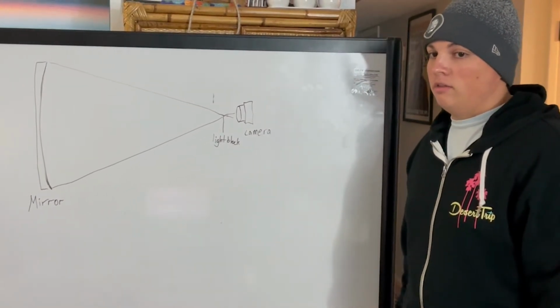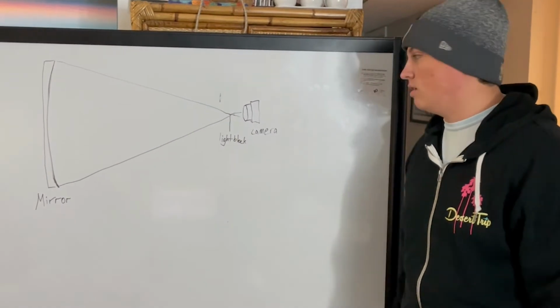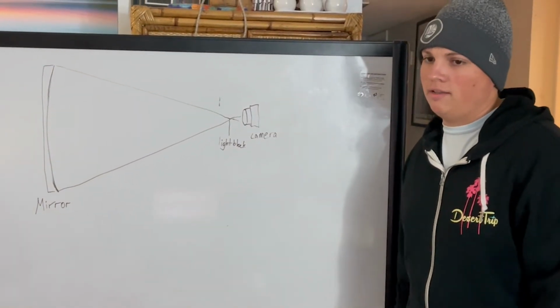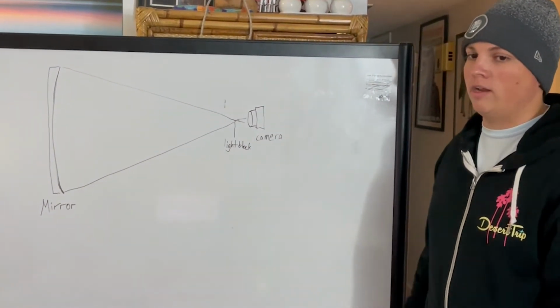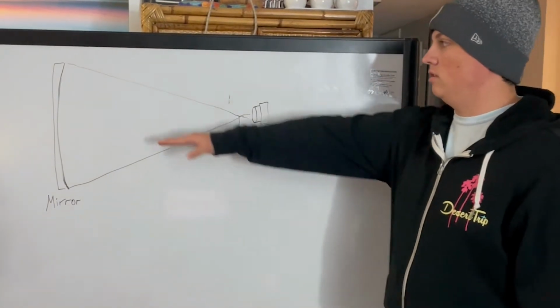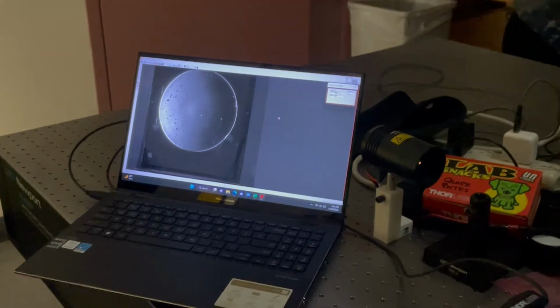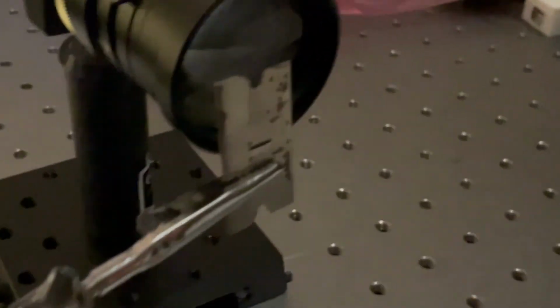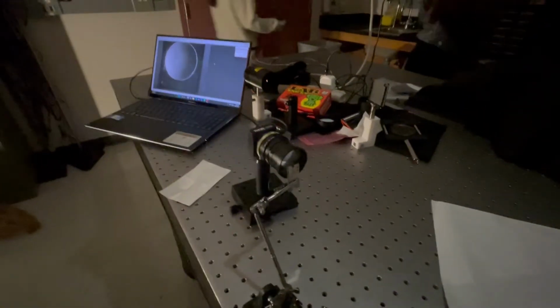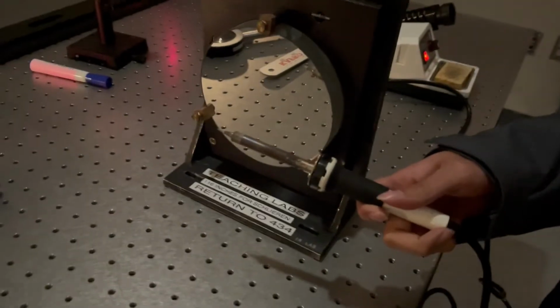So it can either be obstructed more or obstructed less by our razor blade, which will cut off 50% of the light. This will cause a variation in the amount of light that reaches the camera at each point, depending on the indices of refraction in the test area. This variation can be seen as variation in brightness, as captured by the camera. The Schlieren setup takes slight variations in the index of refraction and produces corresponding variations in image brightness. The effect that we see on the camera is called the Schlieren effect.